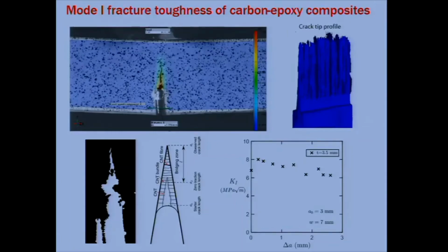So that is the critical point when the cracks start to grow, and following that, they all crack until that point. And this plateau, you can use that as a fracture toughness value for your material. Okay? So now I kind of give you the brief understanding of the stress intensity factor and the fracture toughness.